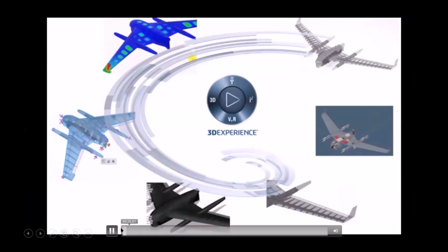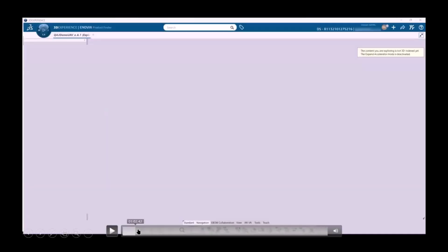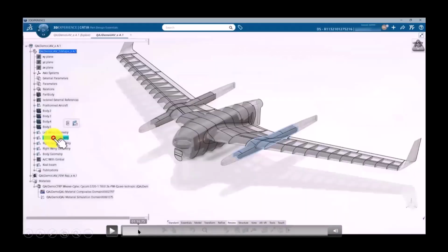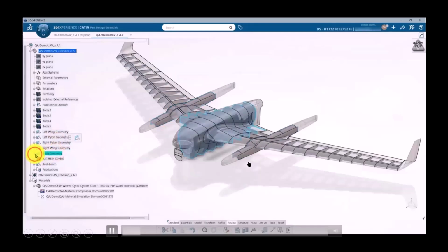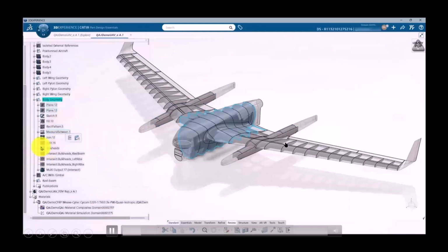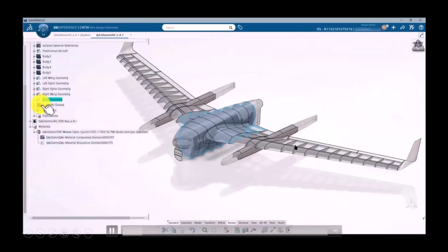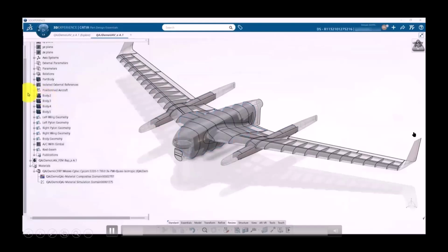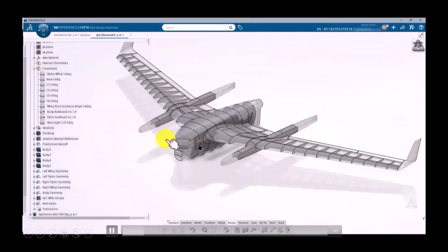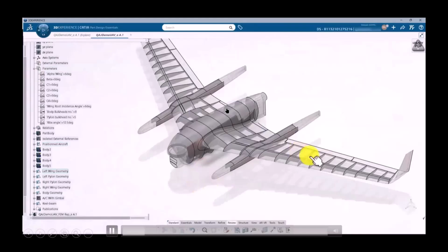Basically, the story here is you design a drone, and what you want to achieve is to find the optimum values of different parameters, like number of ribs or thickness of the shells, because you want the buckling, which is a deformation of the surface of the wings, to be within a 3 millimeter range, and also deflection of the ends of the tails to be less than 5 millimeters. And all this story is showing you how to set up the model, how to constrain it to get where you want by playing with a couple of parameters.